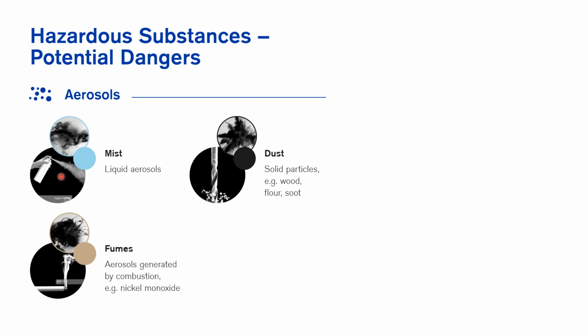Different areas of the mixtures have different properties, of course different in color, hardness, and even aggressive acids. These aerosols become hazardous to health when the particles are inhaled deep into the lung. Even disposable spray cans with flammable and highly flammable content can be problematic in the workplace. Other examples include oil mist from cutting and grinding. So you need to choose the right type of respirator to ensure that you are protecting against this type of mist.